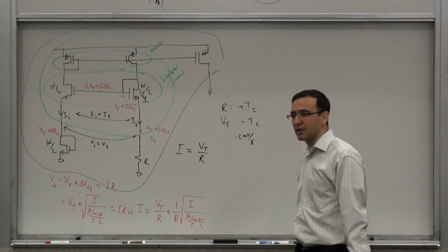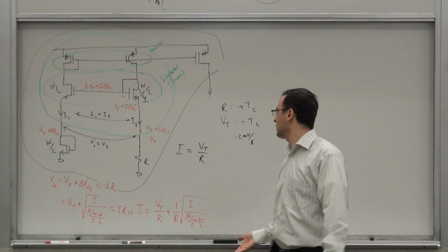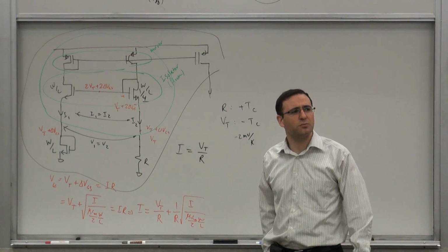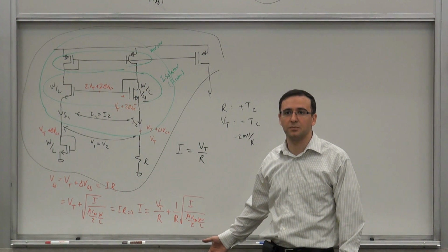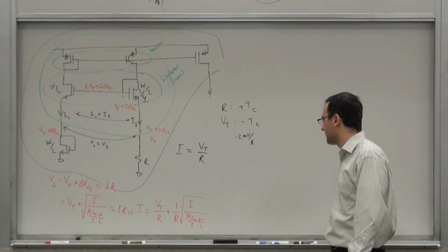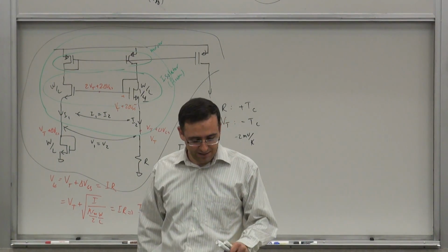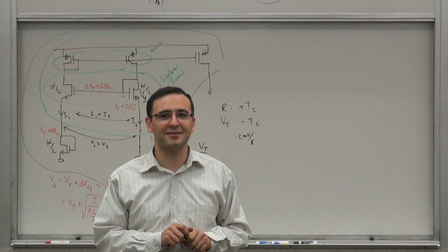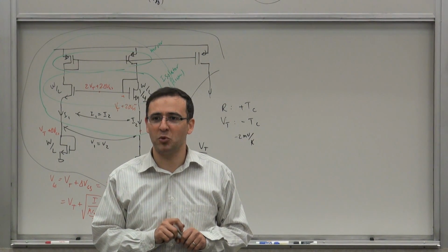It also has process variation. So making a reference with VT is one way to do things. If you want to make something that is just temperature, supply independent, you could do it. And some people still do it for designs which are not very sensitive to temperature. Can you think of one kind of application that has almost no temperature dependence, or where you don't care about temperature stability, because you know you're working in a relatively stable environment?